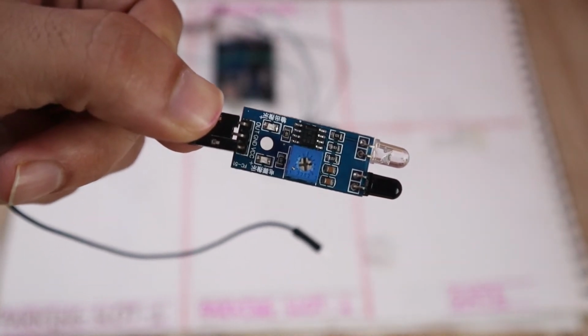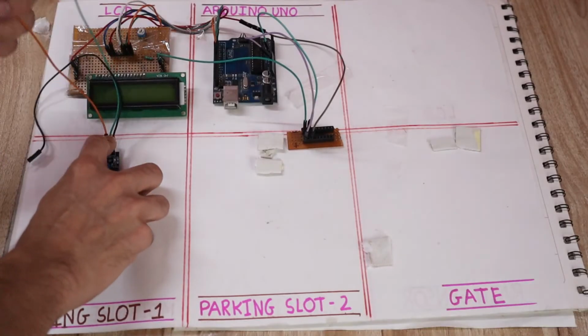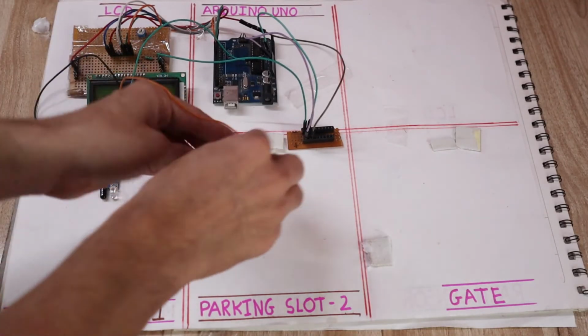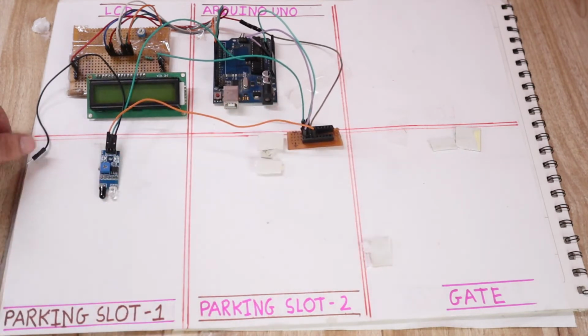So you can see the IR sensor has 3 pins: VCC, ground and out. The simple connection is that we first connect the VCC pin to the common VCC. This is the VCC pin of the IR sensor, and I have connected it to the common VCC here. This is very simple.